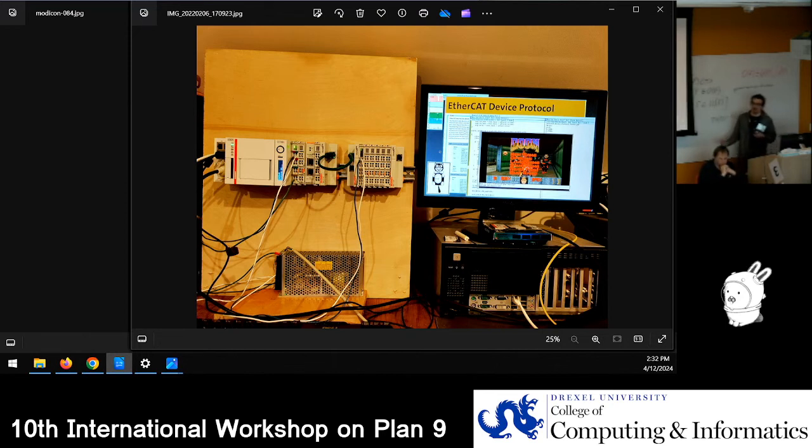But essentially, it's just structures over the wire, and they're read in real time as the telegram, or the Ethernet frame, actually arrives through each terminal. There's a little processing chip in there that looks through the packet as it's coming through in real time. And then if it's addressed to it, it actually starts poking bits into the empty little containers that you have in the frame, which are just data structures.